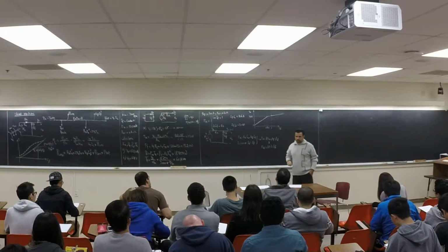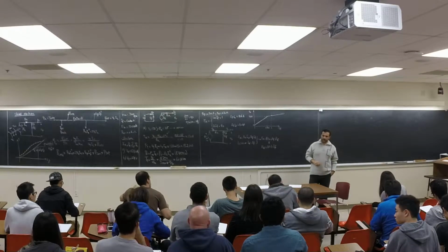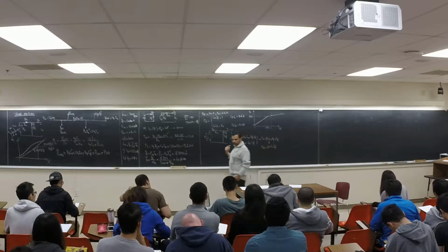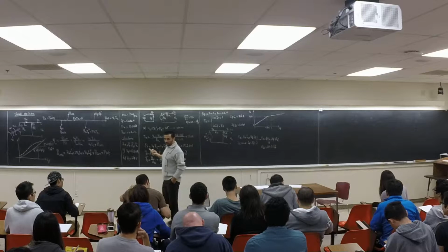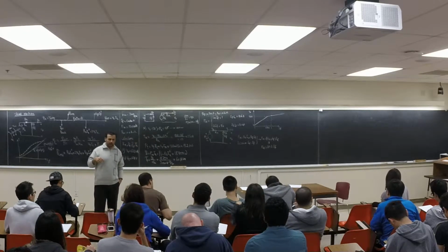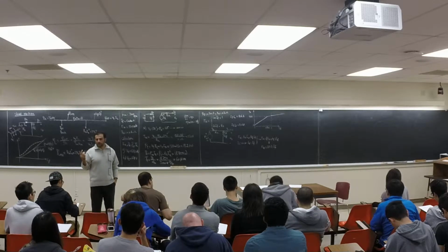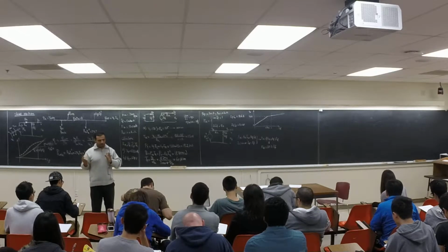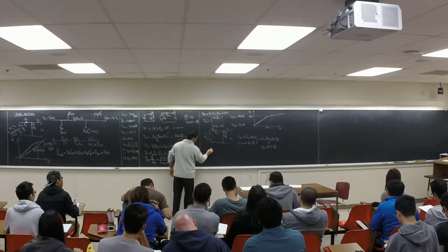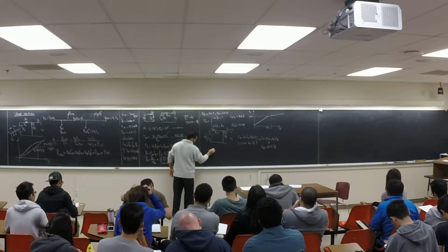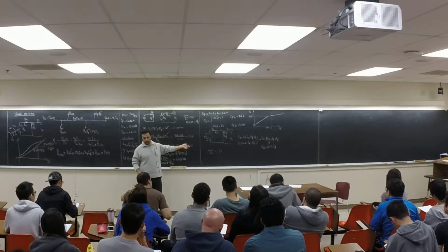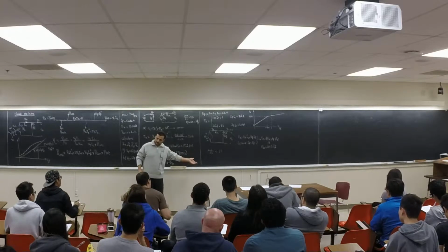right? If I would have ignored the voltage drop under resistance, how much would EA have been? 20, right? Now, considering the voltage drop across the armature resistance, it is 20.2, right? So how much is the difference? 0.2 over 20. It's 1%. It's a 1% error if I wouldn't have considered the 0.2, right?